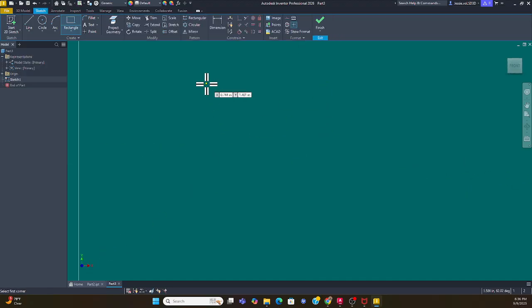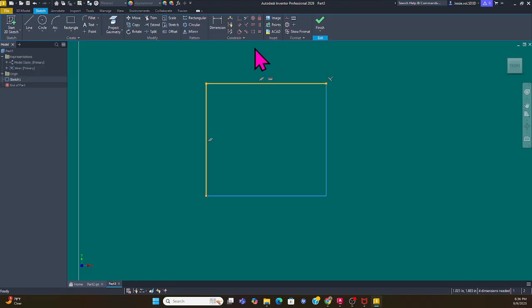All right, what we're gonna do, I'm gonna go ahead and draw a square. There's multiple ways of doing these things here. So what I'm gonna do right now is teach you guys some constraints as well. I'm gonna click on that and this as well by holding the shift key. I want to set those to be equal. As you can see, they are equal now. And because they are equal, everything here is equal. Parallel lines, parallel and perpendicular, so it's opposite or parallel and congruence. So we got that done.